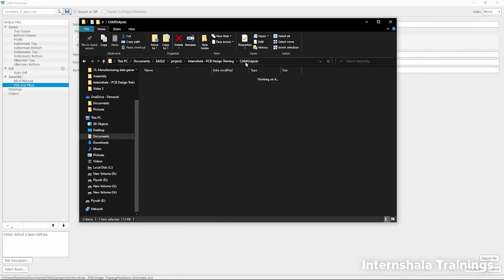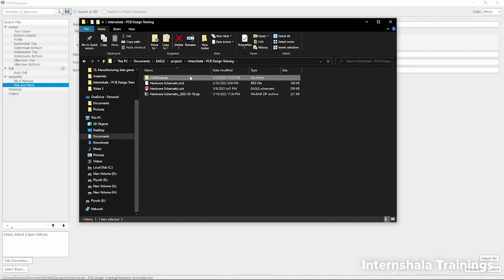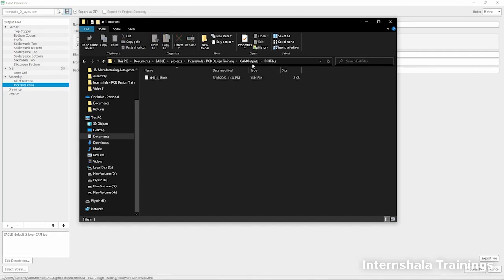Alright, so that was all about the Gerber data, and I hope that you got every single thing that we discussed regarding the Gerber data. Gerber data constitutes all these files, and we need to send these Gerber files to the PCB manufacturer. Along with that, we need to send this drill file to the PCB manufacturer to get the PCB manufactured. Okay, so these two are important files. Whenever we have to assemble the PCB, at that time we have to send these three files: the pick and place file and the bill of material. All right, that's why they are called assembly files.